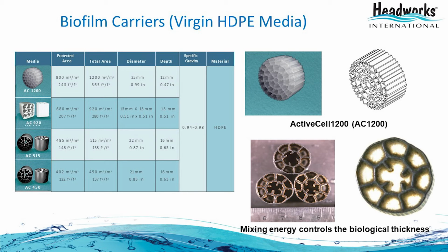Typically, the larger openings can handle much higher loadings compared to smaller openings, which will have lower loadings and may have specific applications in ammonia removal or nitrates removal. Whereas for industrial applications with high loadings and high temperature, typically the larger opening media is used.